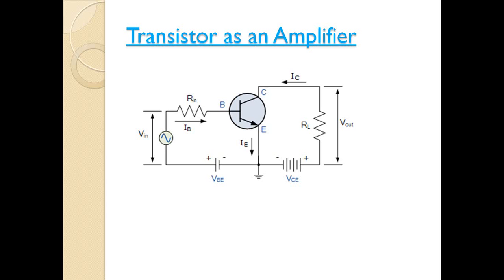Where IE is the quiescent emitter current. Now if you substitute RE dash as 40 ohms, alpha dash as 1, and RL as 2 kilo ohms, A becomes 50 directly. It means what I already explained. Please let me know the answer. Students, please think.